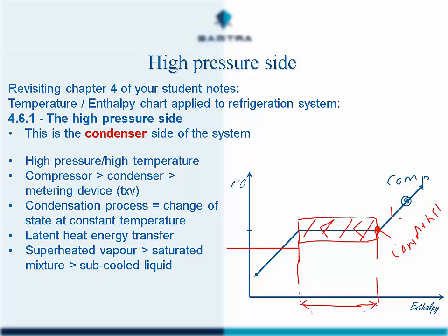So condensation starts, vapor turns to liquid, and then at the end of the change of phase, where we have 100% liquid, if we are still removing heat energy, then we can cause the temperature of the refrigerant to cool down. Okay, so there was a major removal of heat energy in the latent heat phase in this area, and then